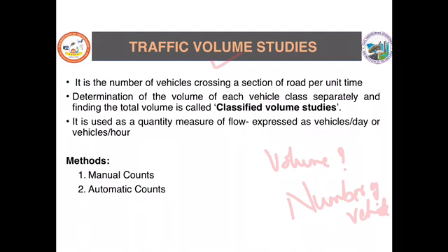being constructed. Now, with respect to the traffic studies, we have one thing called the classified volume studies. I've already told you we are collecting the details about the total number of vehicles expected in that particular place. But in India, we have mixed traffic conditions, where all categories of vehicles, for example, two-wheelers, cars, buses, LCVs, and so on, will be traveling on one single road stretch. Such traffic we call the mixed traffic condition.